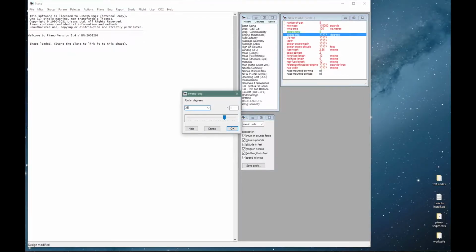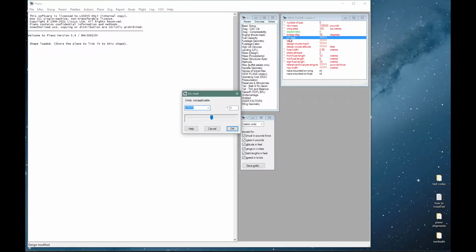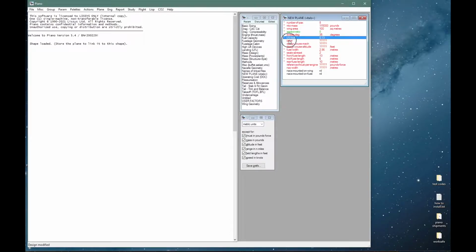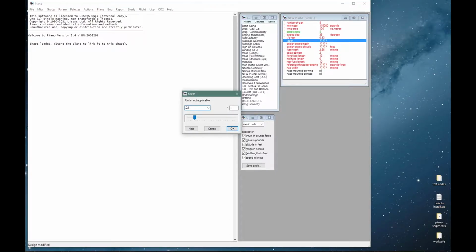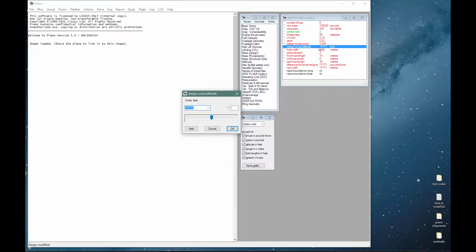Sweep back 35 degrees. You may recall that the 787 also cruises at the typical Mach number of 0.85 with only 32.5 degrees of sweep. However, the Falcon 10X also has to do well at Mach 0.9 and even beyond that. Thickness chord 13%, taper ratio about 0.22. The MMO is given as 0.925. And we'll put a nominal design cruise altitude of about 41,000 feet.